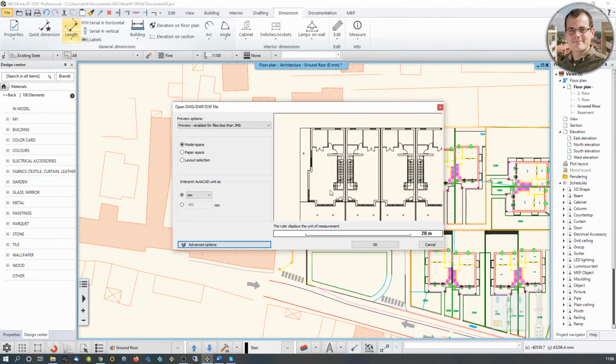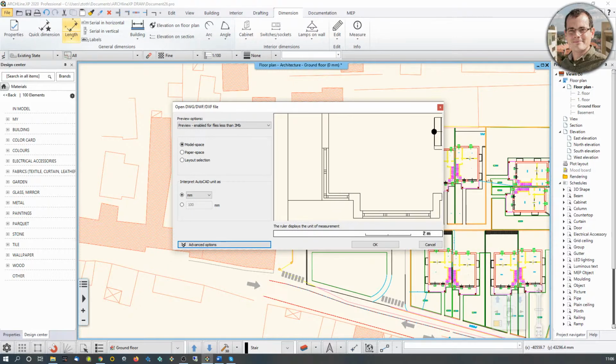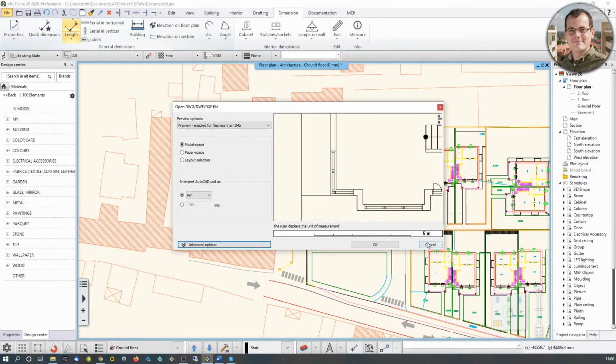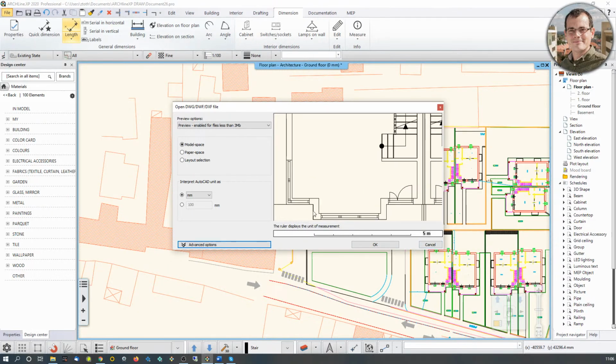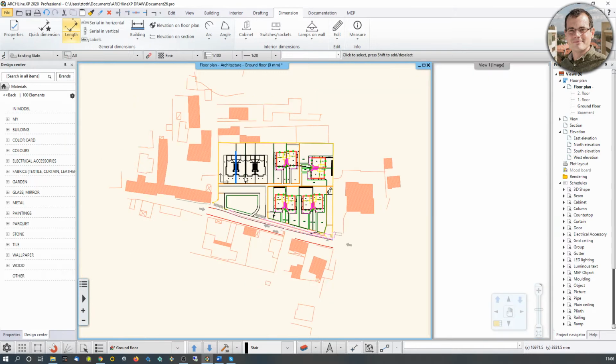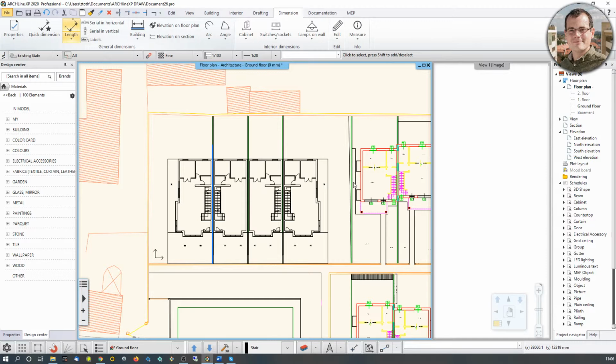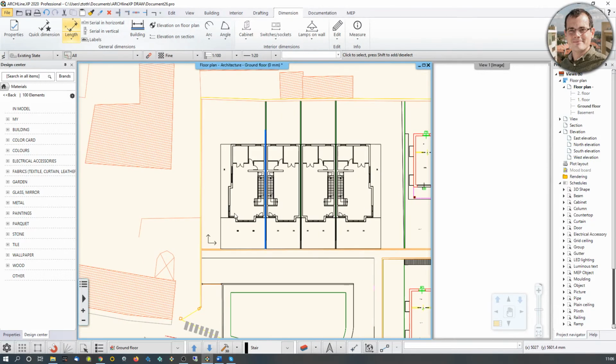Now again, I have a floor plan here with many lines, so I can just zoom in and see if this makes sense. I think if this is 5 meters, then this should be approximately 4, so this one should be good. So I'm just going to accept it. By the way, if things are not appearing in the right scale, you can rescale things. So now you see that the city block drawing and the ground floor is actually lined up nicely.